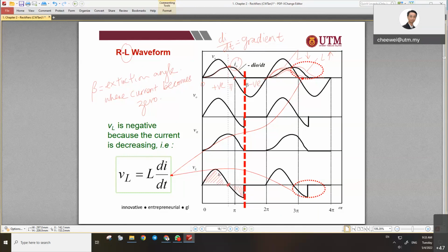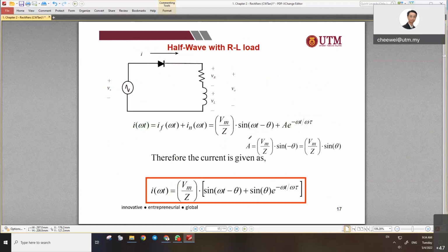This is a sine wave. You finish the sine wave because it stopped at beta, right? So we have to stop immediately with a slash like that. If we went further on, maybe you could have the sine wave complete. But if it's just at beta, then we have to stop immediately at beta. Beta means the current equals 0 already. When there's no current, there's no voltage on the inductor. So this is only VL, only one voltage, VL.